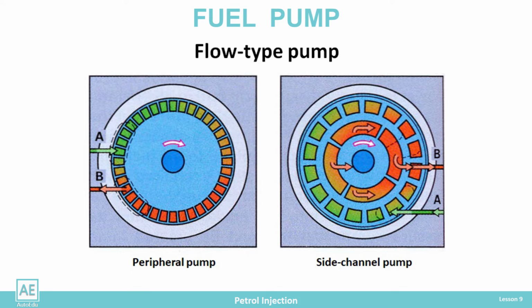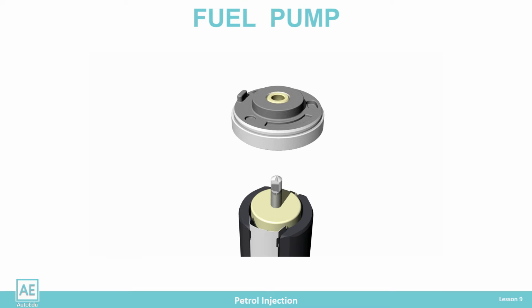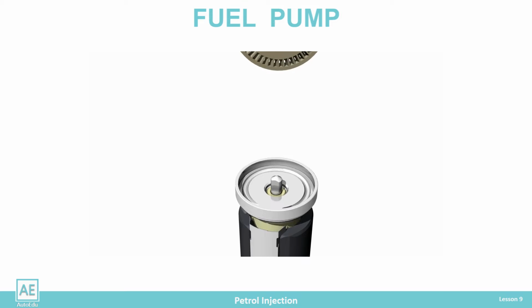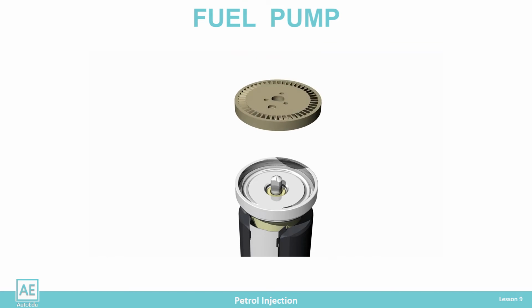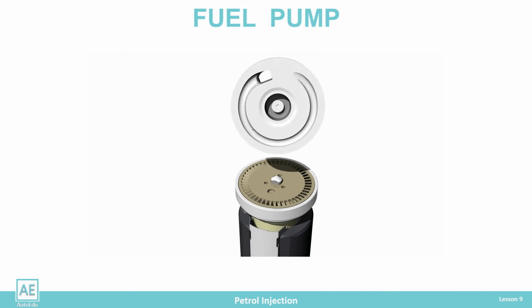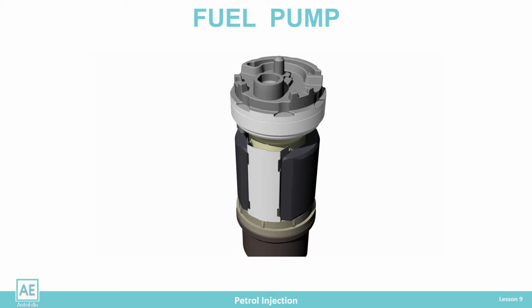When the injection system has a high-pressure pump, as in direct injection and diesel systems, a flow-type pump is used. It has the task of bringing the fuel from the tank to the high-pressure pump. The impeller of the flow pump pushes the fuel with numerous vanes, creating pressure continuously without oscillations. They are quiet in operation and are not sensitive to the formation of bubbles because they can separate them through the degassing bore. However, flow-type pumps achieve a maximum pressure of 4 bar.